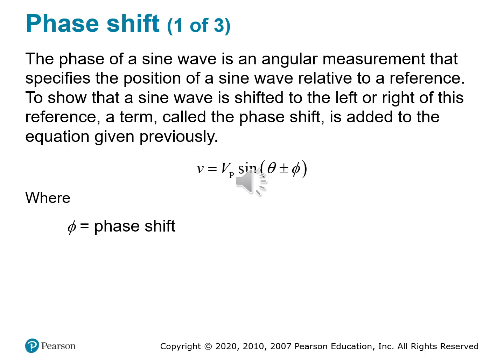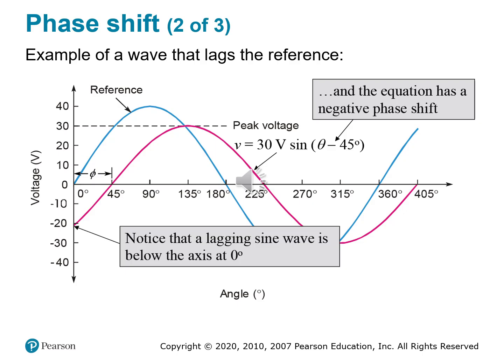And this is how we mathematically describe situations like a voltage leading the current in a capacitive circuit, which we'll talk about in a week or two, capacitive and inductive, or current lagging voltage in an inductive system. Phase shift is especially important when multiple sine waves interact. So in AC power systems, in signal synchronization, and in communication systems, it helps us quantify not just what is happening, but when it's happening in relation to something else. So when a wave follows the leader, we call that phase lag.